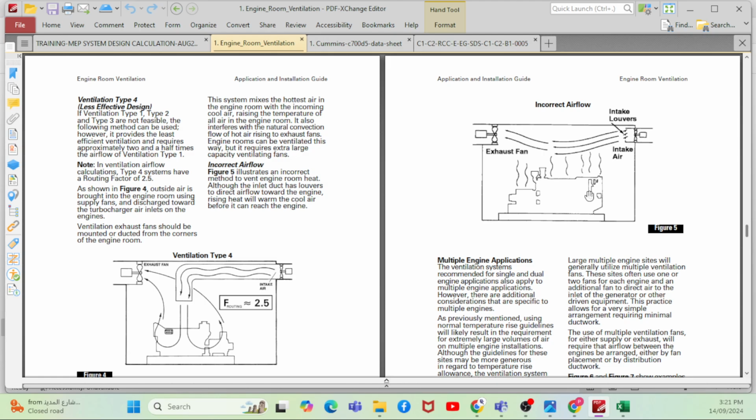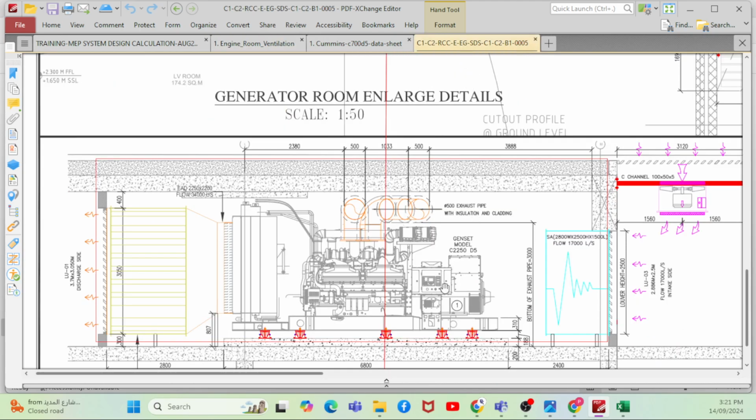Ideally speaking, for all the ventilation requirements that we are following, we should always ensure that the ductwork, whatever we are sizing, should either be closer to the radiator or under the entire generator itself. The ductwork needs to be extended till there. Normally you will not get a chance to run it below, but normally you will get a chance to run it in front of the radiator.